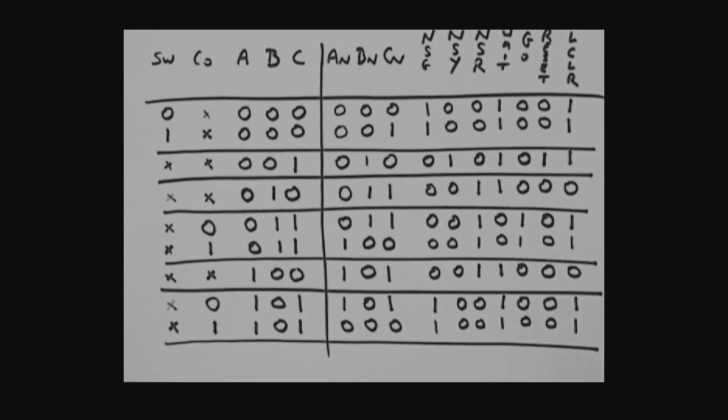The only thing I now want you to do is think about the unused states. As we've said before with the unused states, you might want to put these in your state table so that if you do by some accident get into an unused state, a glitch in the power or whatever, you can know what your conditions will be, and you won't have a situation where you have a green light and a go condition. Also, what I want you to do here is design the logic for this.